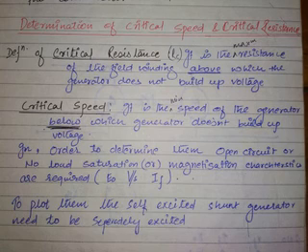Let us consider this is the shunt generator for which we want to calculate RC and NC. This is the armature winding, this is the field winding, both connected in parallel. Now isolate them. This is the armature of the generator. A generator cannot work without a prime mover; it doesn't generate anything by itself. Everything we'll discuss later. Just let us say this is a DC motor coupled to the generator. If you find a generator, it is definitely coupled to a motor. Now this motor is given a DC supply. Let us think this motor is started with its necessary starting steps, and finally it is running at rated speed.